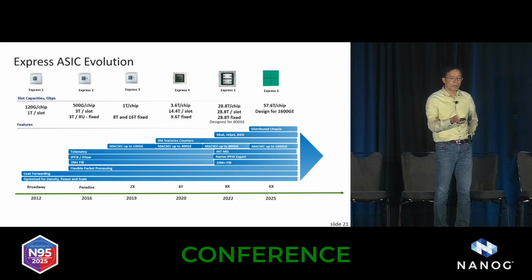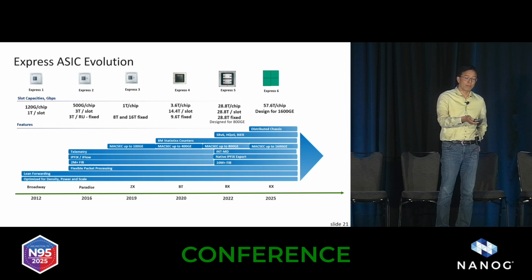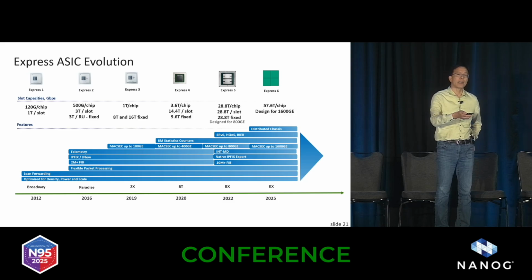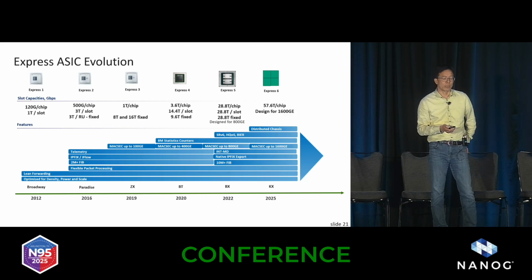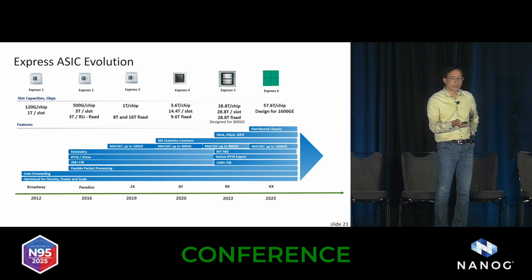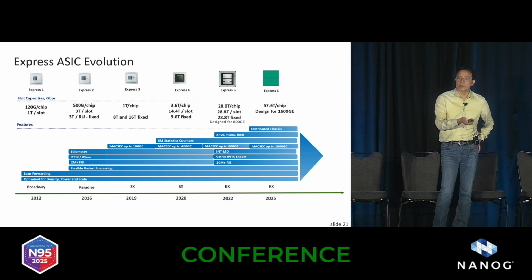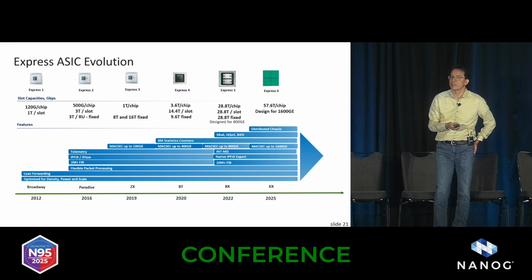But the problem is the interface will also occupy die area around this region, so typically you don't have enough space to put the SerDes around those areas. So deep buffer silicon performance is usually almost half of shallow buffer silicon.